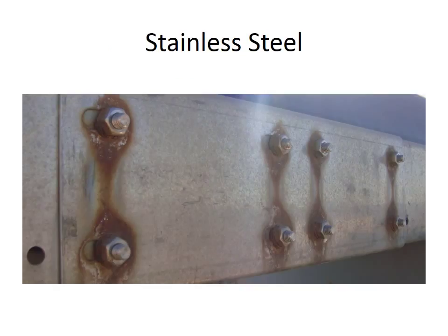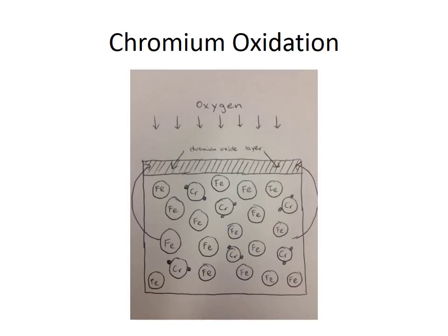Thus, this material was not an effective material, had to be replaced, and needed a substitute that could better resist corrosion. Enter stainless steel. Stainless steel is less corrosive than carbon steel, allowing less to be used, decreasing the weight of the plant, and decreasing the necessary maintenance. In most steels, the iron atoms are oxidized in the presence of oxides, but the increased amount of chromium present in stainless steels causes the chromium to be oxidized instead, which causes a layer of chromium oxide to form and greatly lower the diffusion rates of additional oxide. However, stainless steel is still corrosive. Carbon steel thins, but stainless steel pits, which means that it corrodes in localized areas.